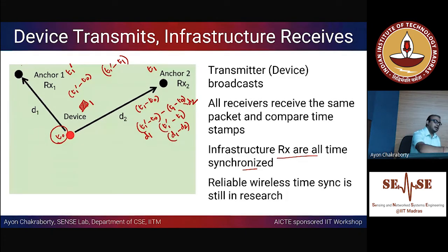So what is often done today is that they are connected to some kind of Ethernet cable, or some cable that can synchronize these timing pulses, the sync clock. If you deploy such anchors, think about the hassle. You are deploying these anchors in the building, and you have to run a physical cable that is going to synchronize the clocks of the anchors. In that way they will have the common reference frame with respect to time.